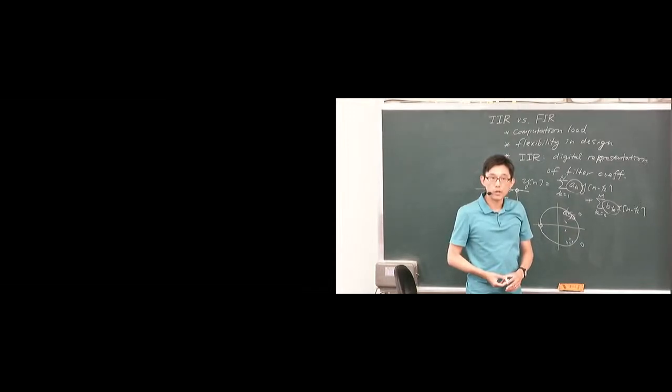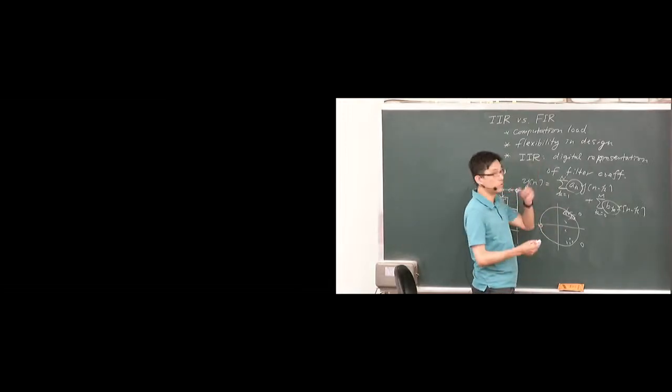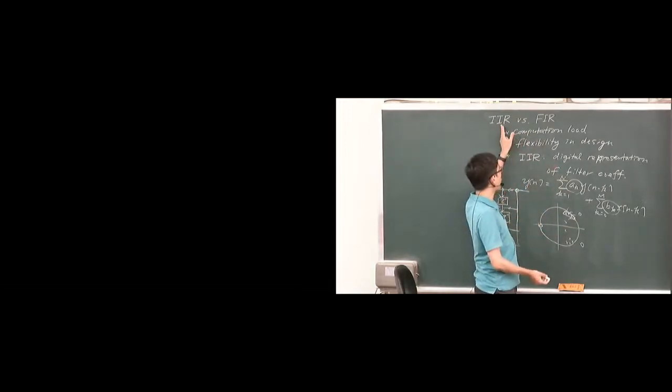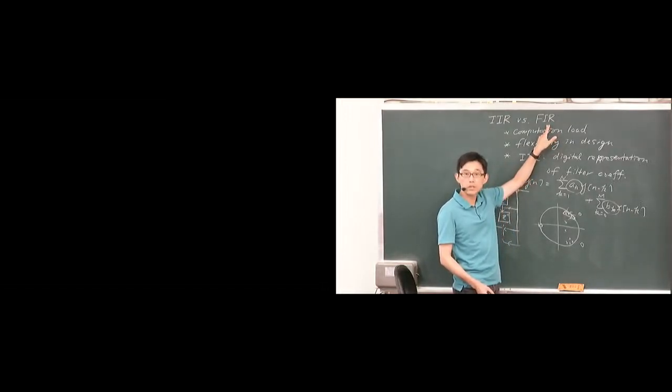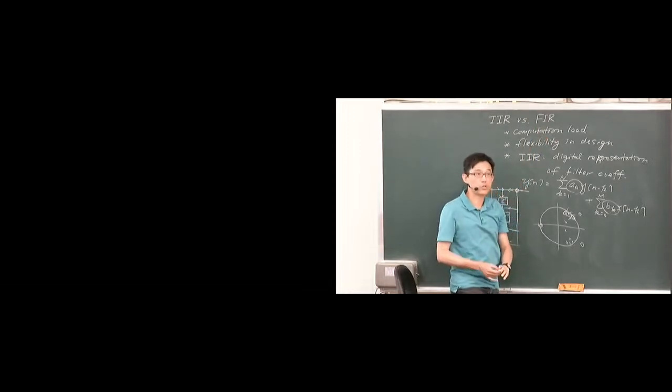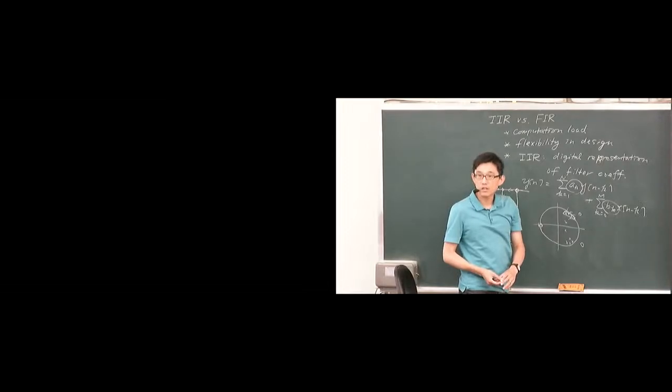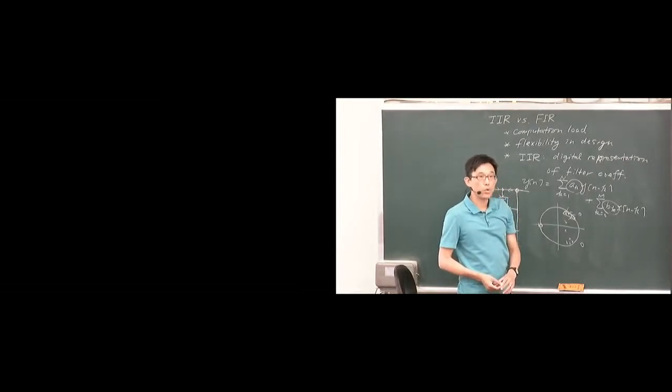But that being said, there's a famous way to accelerate FIR, so that's not the end of the story. I just suggested to you that in the most straightforward implementation, IIR is usually more efficient than FIR when we design low-pass filters, for example. But FIR has a secret acceleration gadget. There's the technique called FFT, fast Fourier transform, which can greatly accelerate FIR filters.